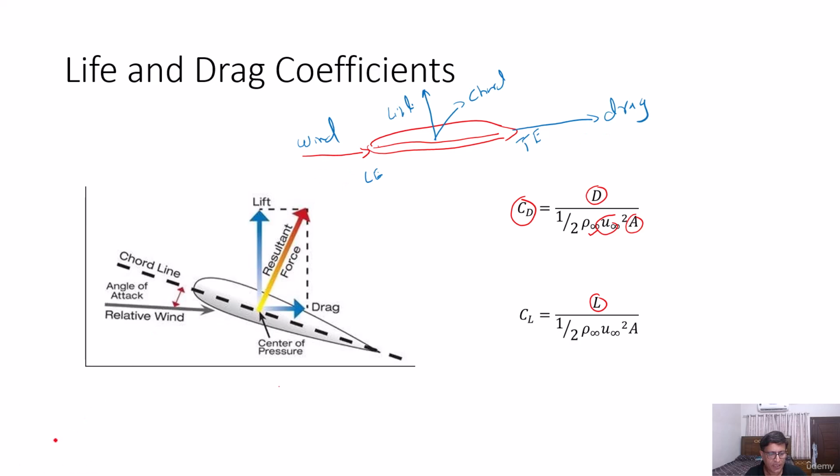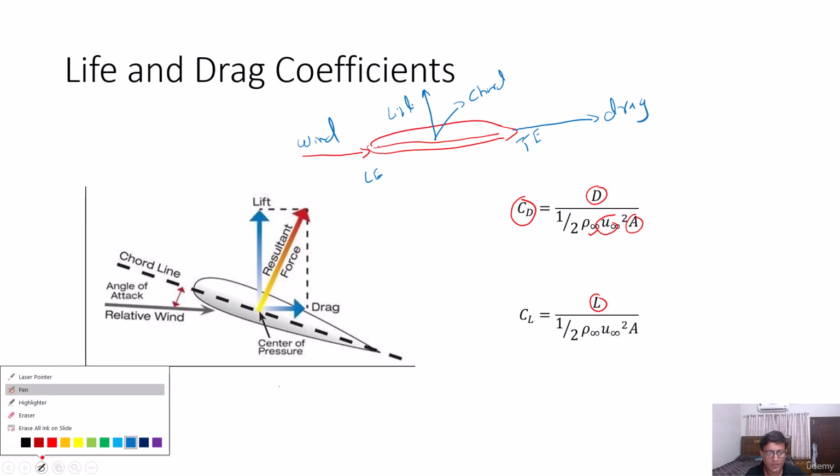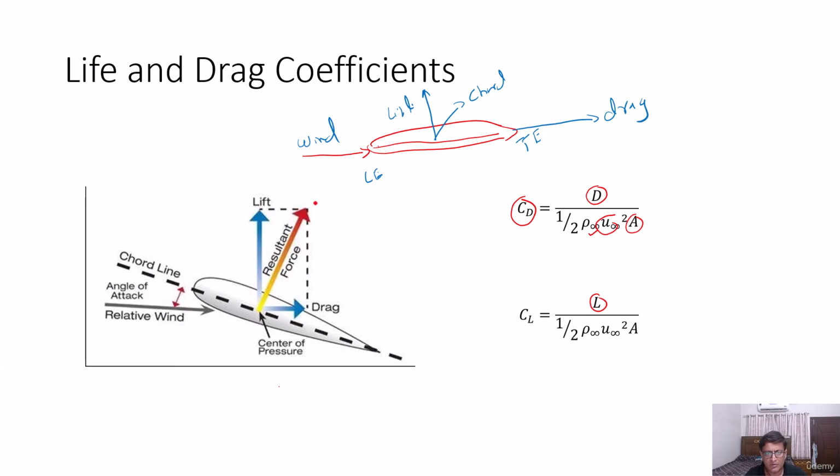Okay, now if I have some angle of attack, in that case what will happen is, let's say now my relative wind angle, it's the same thing as if the aircraft is making the angle and the wind is coming from the bottom, so alpha is here. Okay, so the angle is important, the relative position is important, but not their actual position from the forces calculation point of view. Now what will happen is that in this case the drag will be on this side.